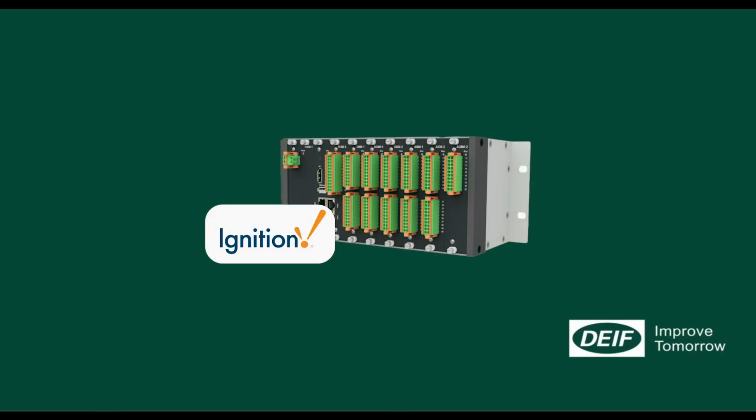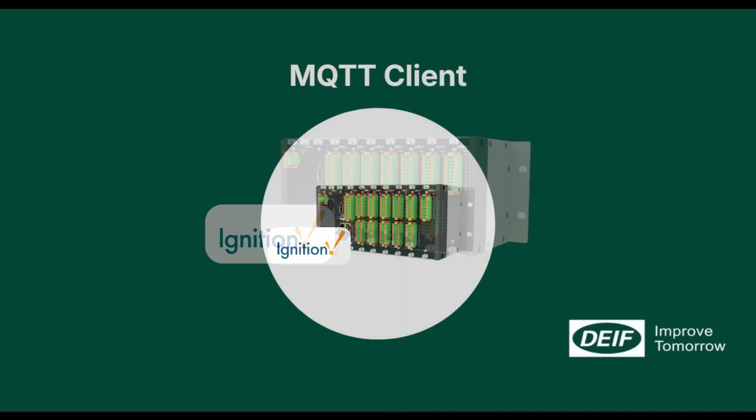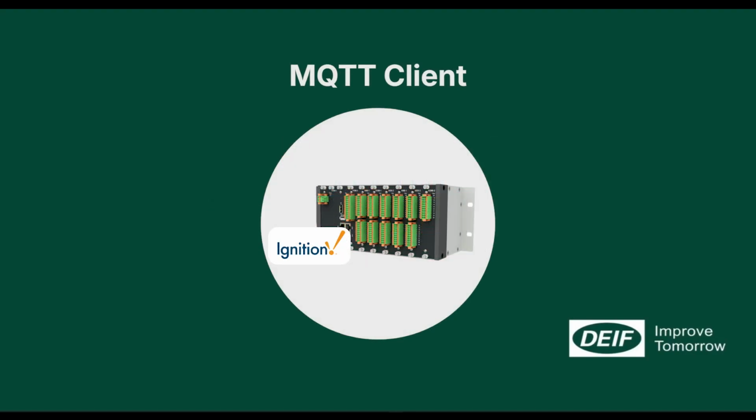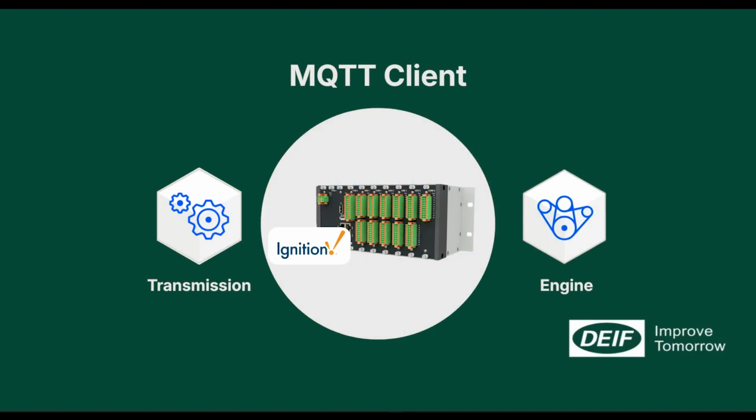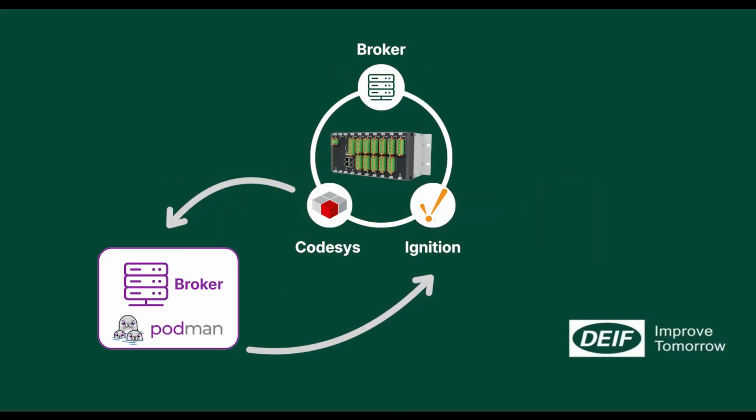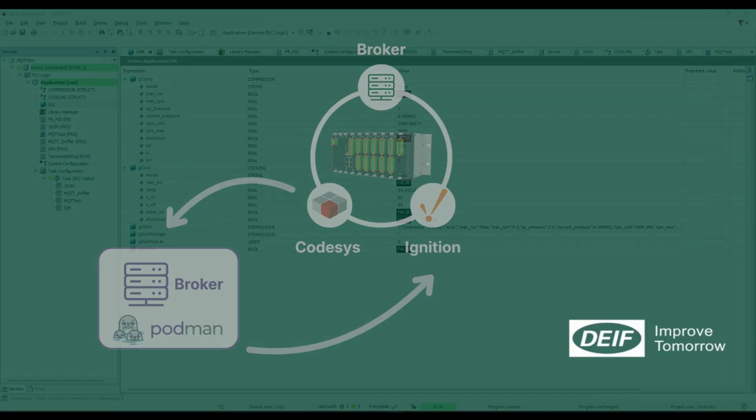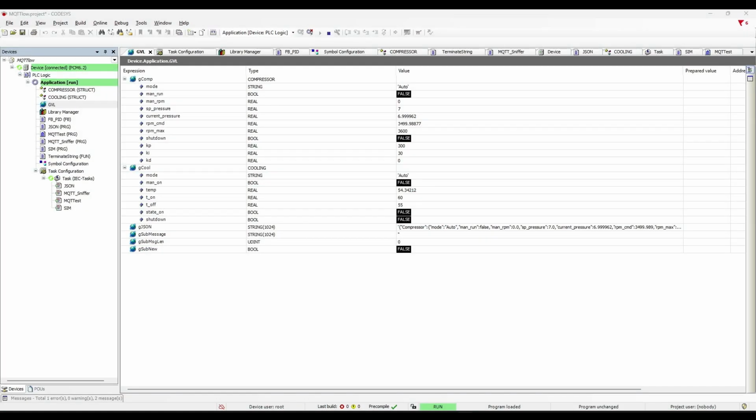In this setup, all components run on the IE650 PLC. Data is generated by a CodeSys application and published to a broker running in a Podman container. That data is then consumed by an Ignition project, which can optionally publish data back to the broker or forward it to external systems.